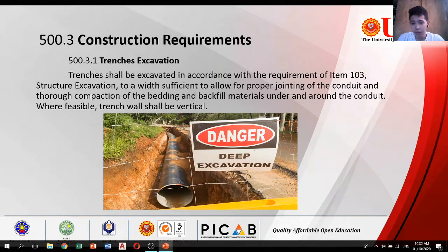Where feasible, trench shall be vertical. The completed trench bottom shall be firm for its full length and width. Where required in the case of crop drains, the trench shall have a longitudinal camber of the magnitude specified.